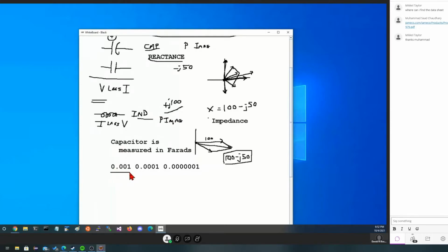Somebody tell me how we would verbalize that particular measurement there. Frank? That would be 1 times 10 to the third power. Yeah, well, let's put a unit on it. Let's say we're using farads. So what would we say? I actually meant to the negative third power. 1 times 10 to the negative third power farads. Okay, so how would we say that? Scott? 1 millifarad. Yeah, except with capacitors, this is the tricky part. Instead, we would say 1,000 microfarad. A little odd, but that's what we would do.